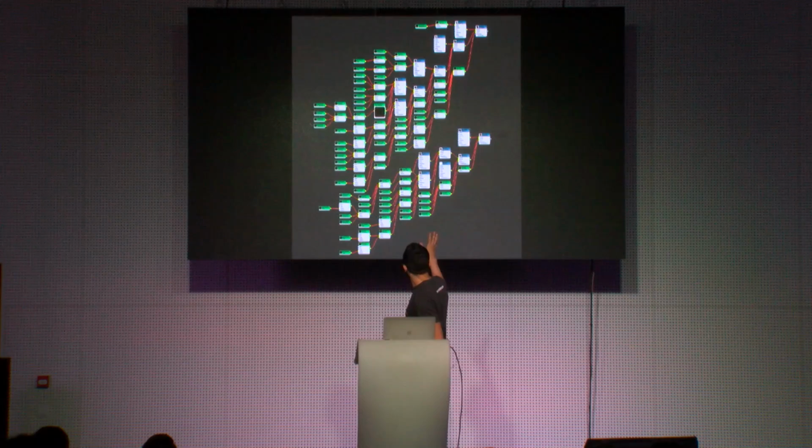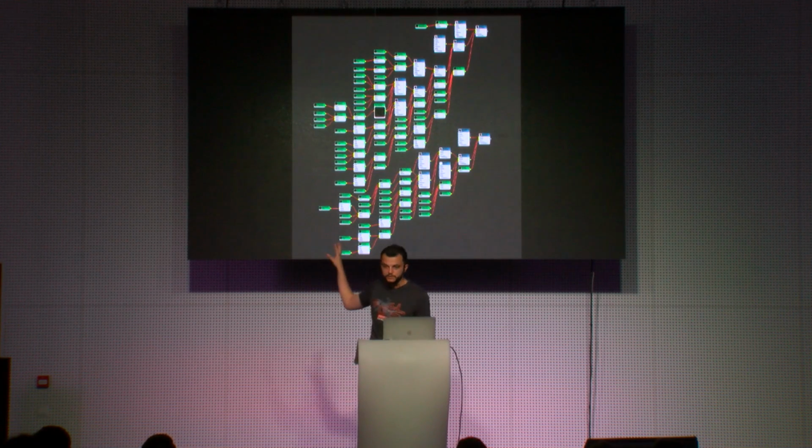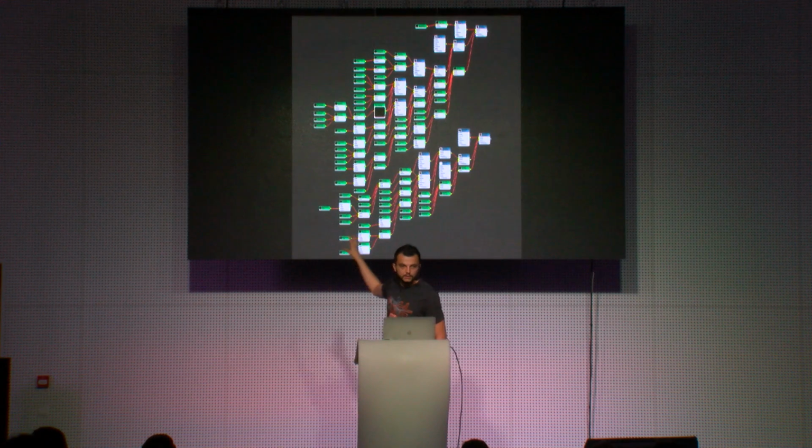Also, we have complex textures like ambient occlusion, which is ray-traced ambient occlusion, which can be used anywhere in the procedural tree. For example, you can blend between two different materials, two different BRDFs, using an ambient occlusion texture, whose radius can come from a triplanar texture, which projects noise and bitmaps and whatever. It usually ends up looking something like this. This is in 3ds Max, from a real user production scene.